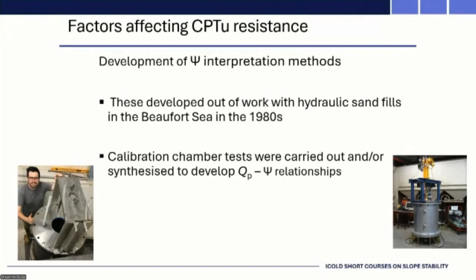In some of the more modern chambers, you can apply a horizontal and a vertical stress, so you now know what p' is. You saturate it, put it under back pressure, then drive the cone in and measure what the cone tells you. And you know what the cone should be telling you because you've set the sample up at a known state: void ratio and mean effective stress. So you push the cone in, and if it doesn't agree, you come up with modifications or change your theory.